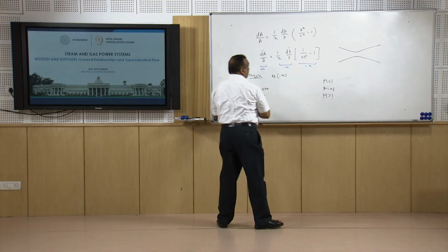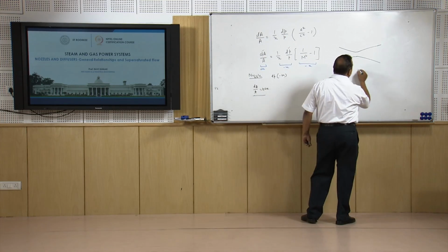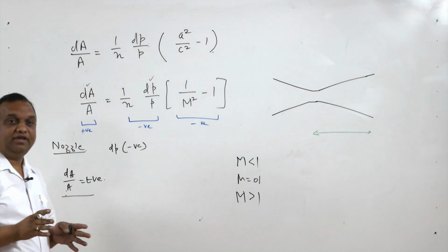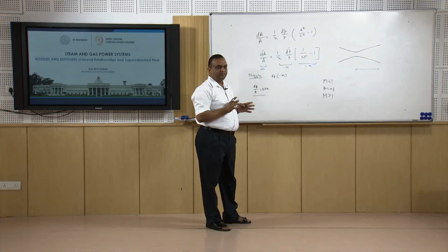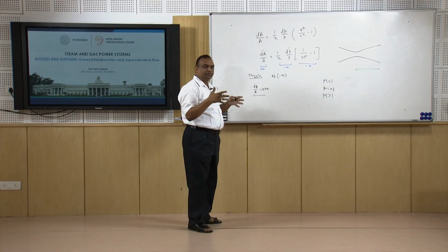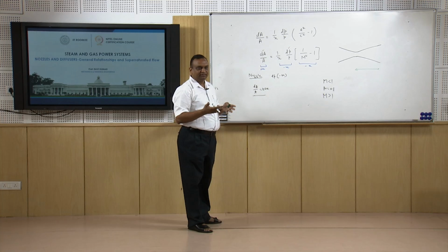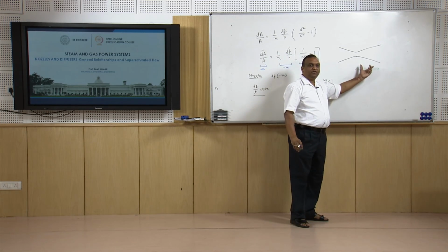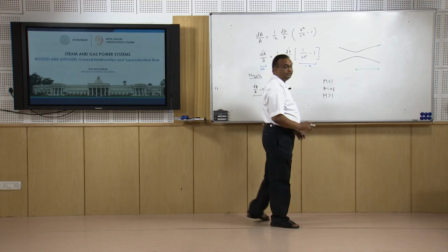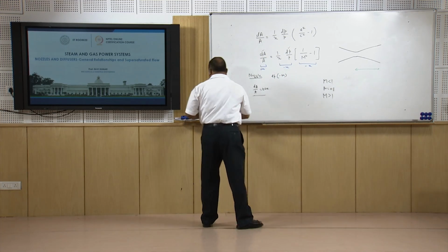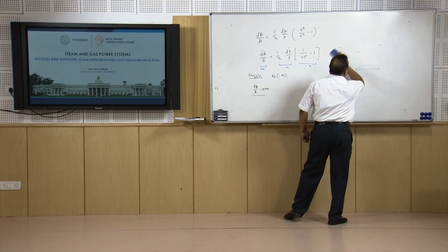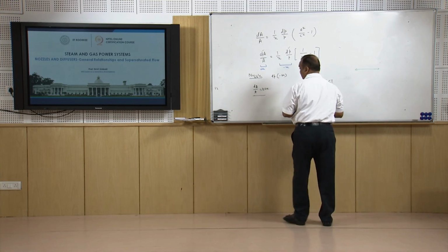It means in this area, the velocity will increase and the cross section area will also increase. Normally, when we deal with fluids and reduce the cross section area, the velocity increases. But in the supersonic zone, if you want to increase the velocity, we will have to increase the cross section area. In most nozzles you will observe that these two lengths are not equal.